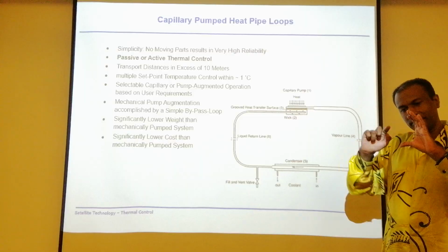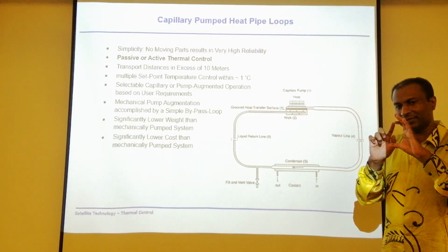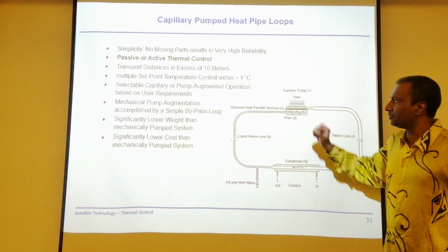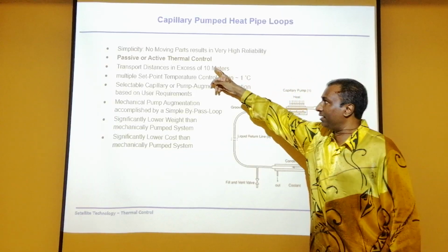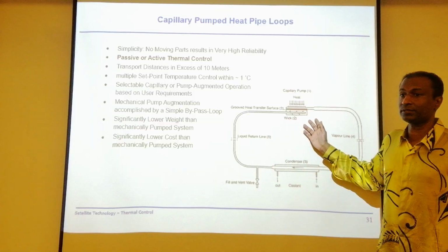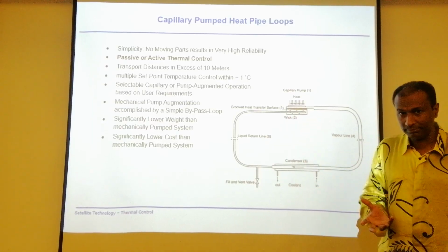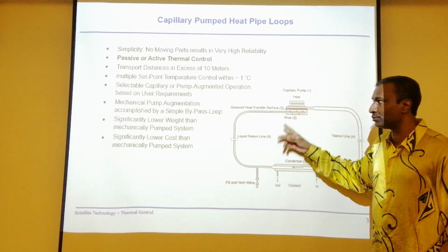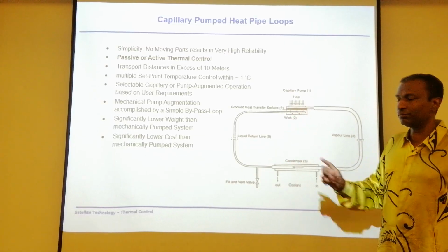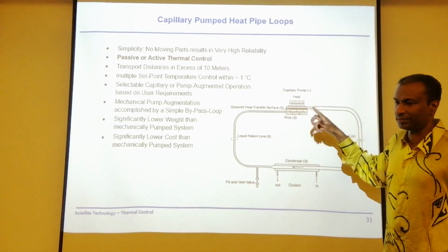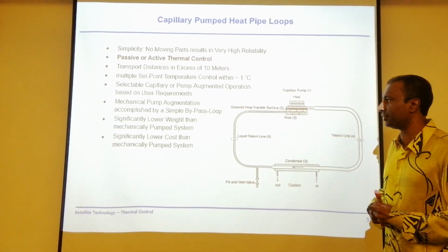So it's helped by the actual design inside, and there is no electricity whatsoever. It is just the design inside. And as I've said, you can have passive or active thermal control using the system. Again, remember, if you have a pump, you don't have to have two loops. You can just have a single loop with a fixed pump. The fluid is actually recirculating to transport your heat.